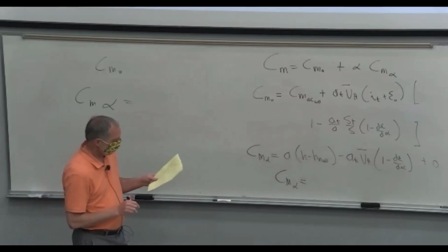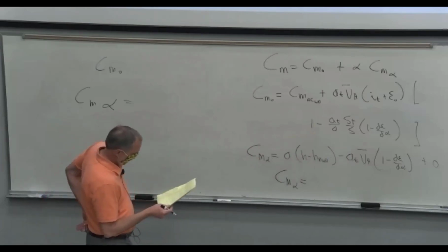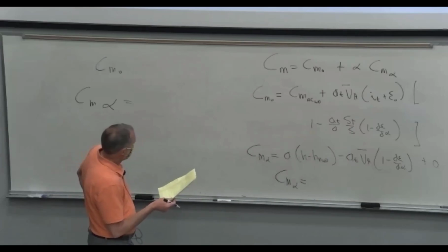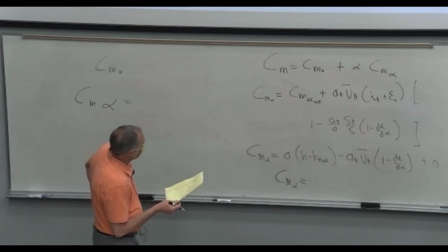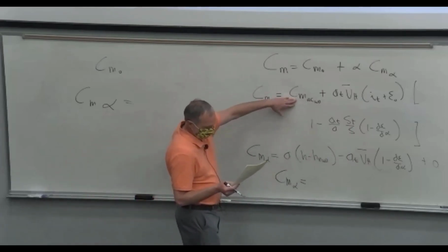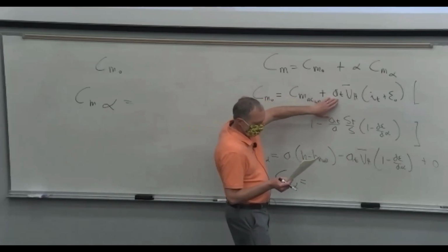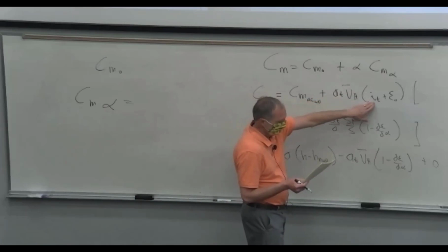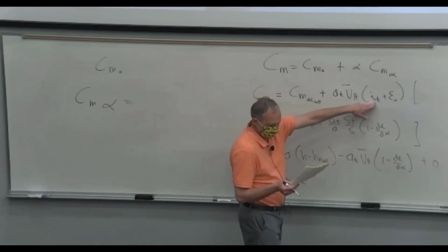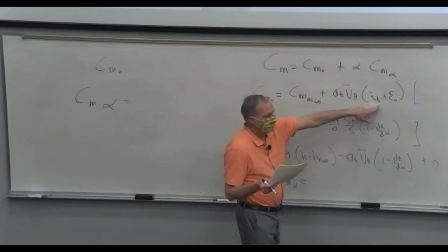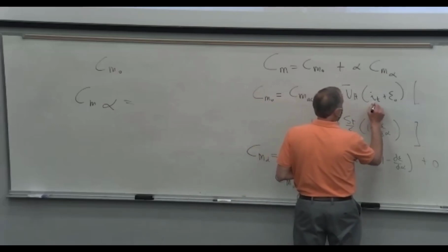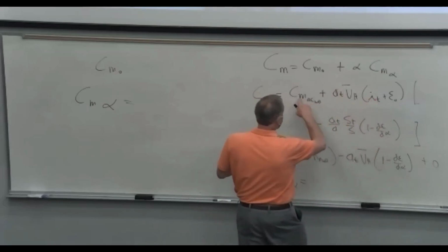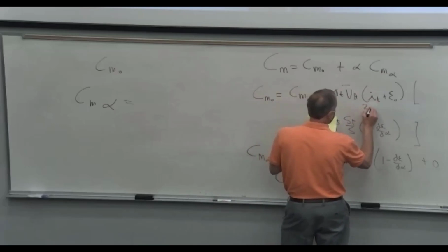There's a lot of terms in here. Let's make sure I wrote the formula right. This is Cmac of the wing body. I gave you that number, right? a_T, V_H bar. We calculated that. We got that right. a_T was given. Oh, what are you doing for this? You're putting in 2? Yeah, so you've got to convert this to radians because this is all in radians here. So this is 2 times pi over 180, right?